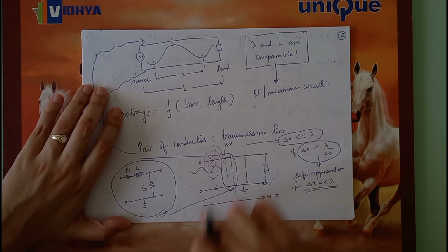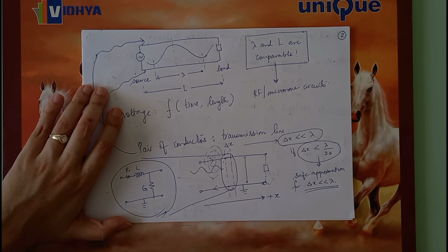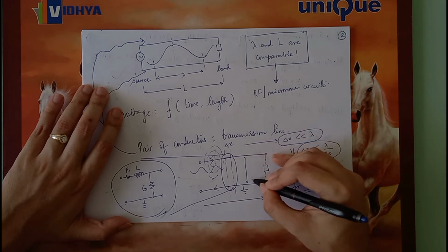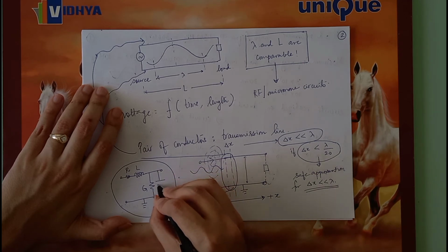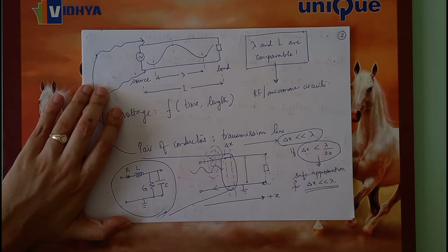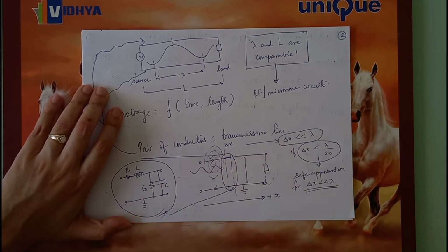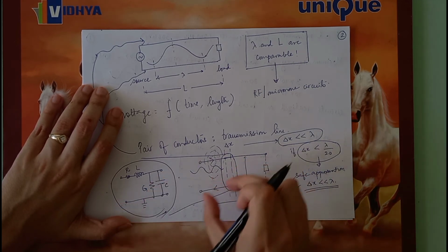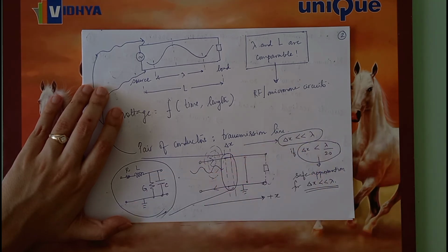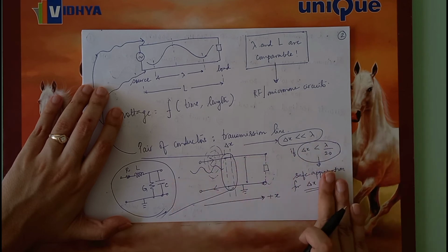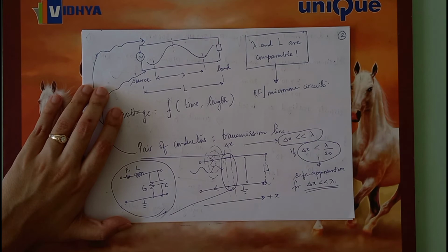Finally, we have two currents which are flowing in opposite directions. Obviously, there will be different charge accumulations along the two conductors. So therefore, this will cause some capacitance C. Now, notice one thing. We have only magnified what is inside this small delta X. For the whole length of the conductor, there will be multiple such circuits, RLGC, RLGC, RLGC.